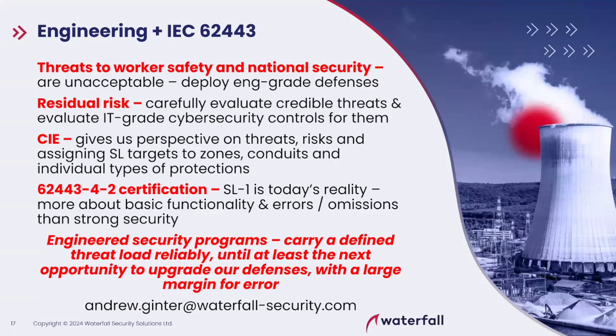That model is still widely used. It's still applicable. The reason people ask if it is going away, 9 times out of 10, is because they're thinking of the industrial internet, where you've got edge devices connecting straight out to the internet with an encrypted connection through 7 layers of firewalls. And intrusion detection is blind to this because the connection's encrypted and you can't see what's inside. It might be good stuff. It might be attacks coming back. We just don't know. That's sort of a shortcut through the Purdue model.